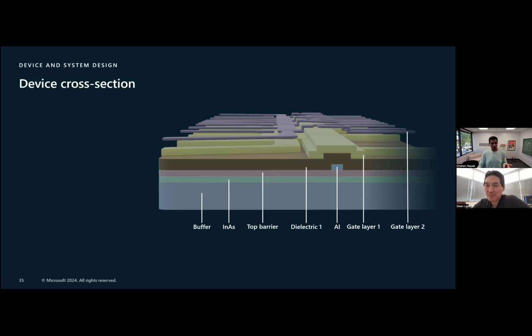Now, the barrier layer actually has to do a second thing, because the dielectric is one of the main sources of disorder. All this relatively pristine semiconductor growth, and even superconductor growth, is done within the MBE machine, ultra high vacuum, high purity. The dielectric is one of the places that's dirtier. It's an amorphous material like aluminum oxide or hafnium oxide. And so there is significantly more disorder, particularly at the interface, but not only at the interface, within the dielectric. So we want the barrier layer, if possible, to keep that disorder as far away as we can. So a thicker barrier is actually helpful for keeping the disorder further away.